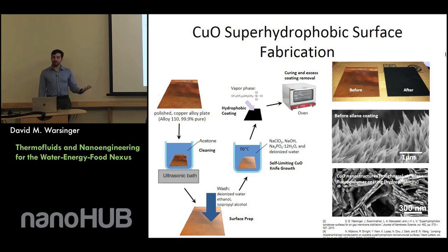We've been fabricating a variety of nano-engineered condensing surfaces to improve the performance. One of these is shown here, creating these blade-like structures which give you extremely high roughness and thus really high contact angles, like 172 degrees. As a result, you can get jumping droplet condensation, which can give you really enhanced mass transfer coefficients. We're also looking at other types of enhancement, such as rapid draining through hydrophilic channels and other hydrophobic areas, with the goal of decreasing the overall gap size.